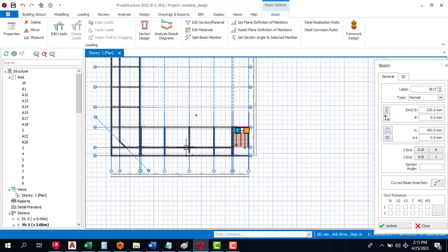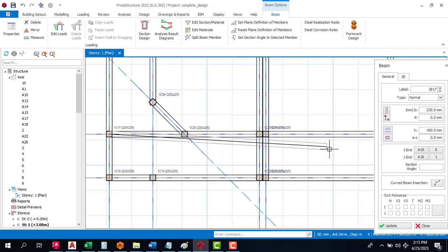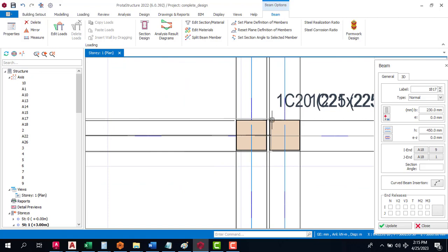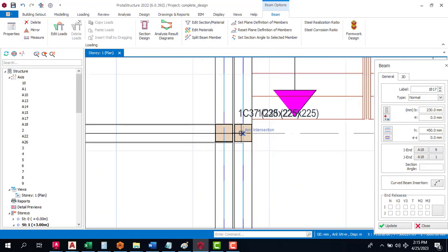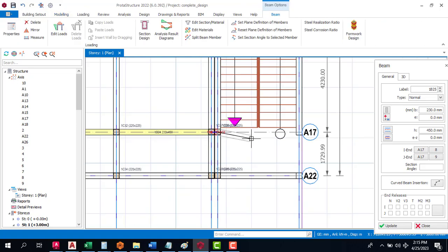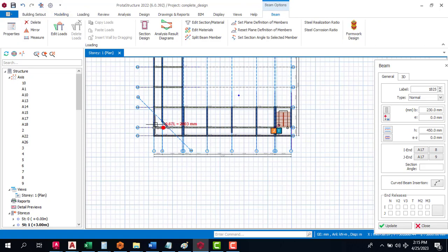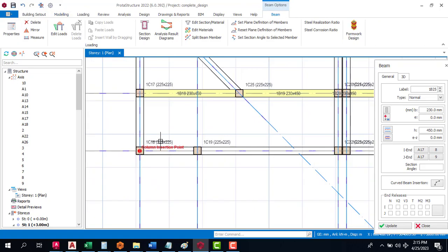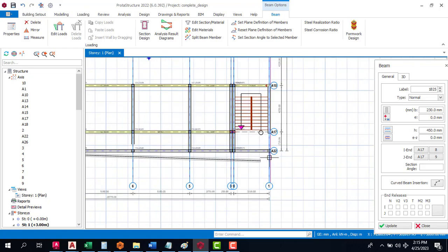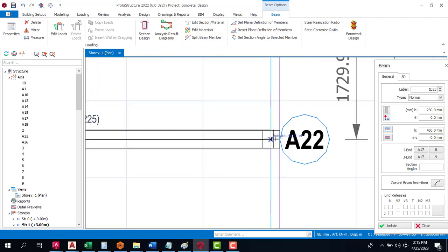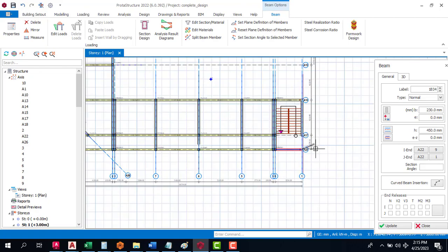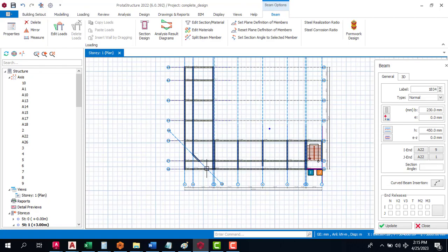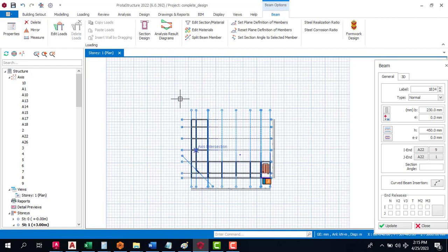Okay. So in the main design I have an expansion joint here, so that is why you are seeing this space. You have to always introduce an expansion joint whenever the span of your building is getting to 30 meters. By code of practice you are supposed to introduce an expansion joint, okay?